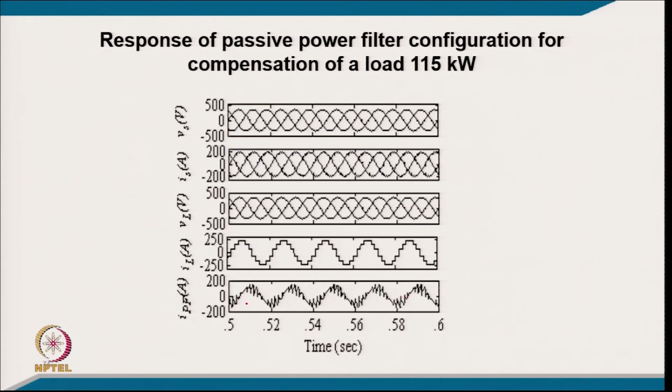So, it has a reactive power, you are looking that fundamental current is also there, that is reactive power in it, okay, and that is the reason this has a unity power factor on the supply side in spite of drawing the reactive power. So, reactive power is provided locally by the passive filter, and typically harmonics are also met locally, they do not go to the supply system.